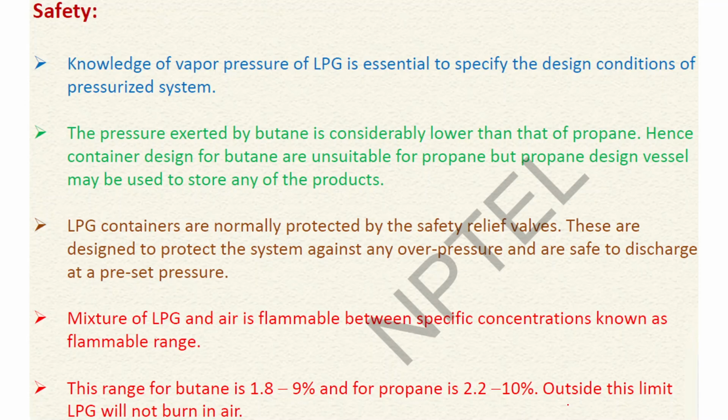Coming on to the safety concerns related to LPG. The knowledge of vapor pressure of LPG is essential to specify the design conditions of a pressurized system. The vapor pressure of LPG should be known so that the design of the vessel to store this LPG can be easily determined.